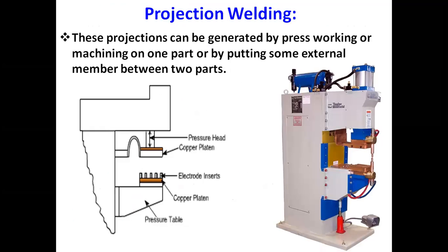Out of the many inspections, the first one is visual inspection. Visual inspection means a human operator visually examines the weldment. He checks the different parameters, that is, confirms the dimensions, warpage, cracks, cavities, incomplete fusion, etc. If there is any crack, or any cavity, or any incomplete fusion, this visual inspection can be performed by a human operator.